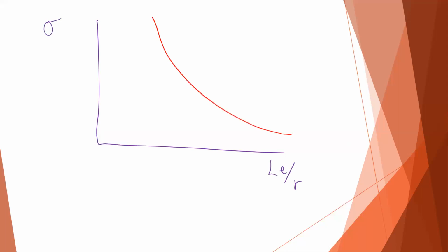So if you plot that slenderness ratio versus stress, Euler tells you that this is your capacity, and as you get shorter, you get significantly more stress capacity. But there's a region in which you're actually governed by your yield stress. There's a region in which, even though Euler says you get this much capacity, you're never going to experience that because your member will yield or fail due to a lack of strength before it becomes unstable.